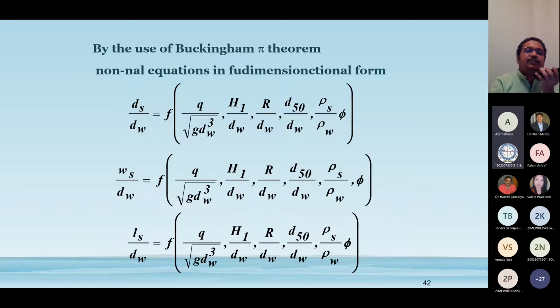Here, depth of scour relatively, I considered the tailwater depth very important; many may take H here, but if you throw something in water, how much you hit depends on it. So from the Buckingham Pi theorem, this one is the Froude number, this one relative head, then bucket radius, then bed material and tailwater depth, and this is the constant you may remove, since with only civil engineering we consider only water.